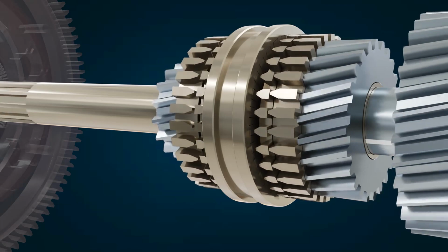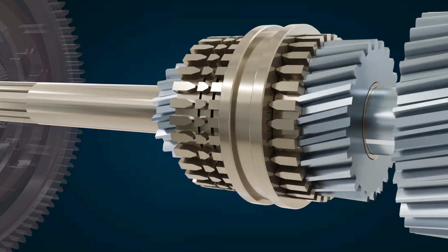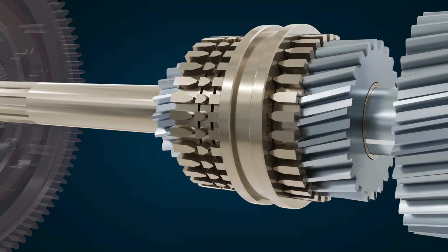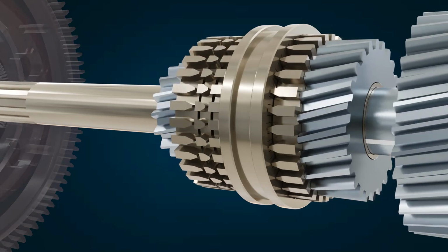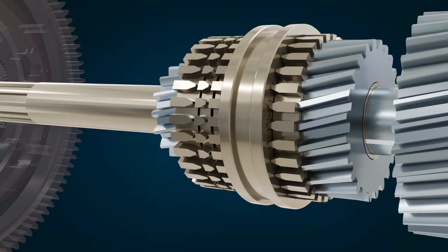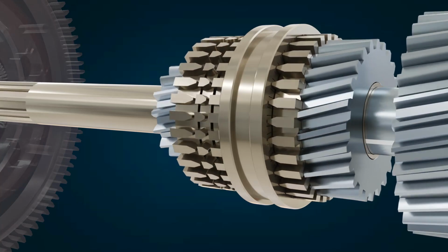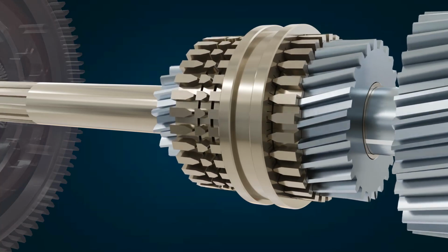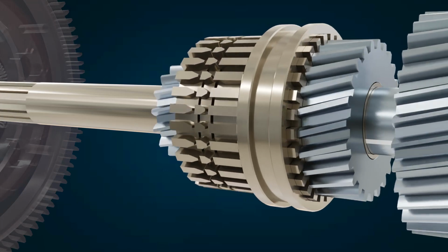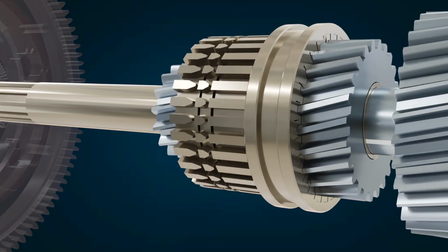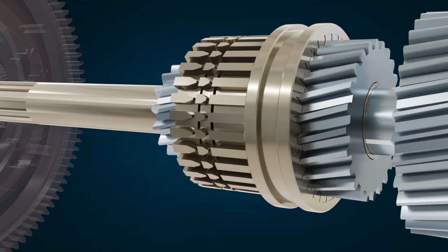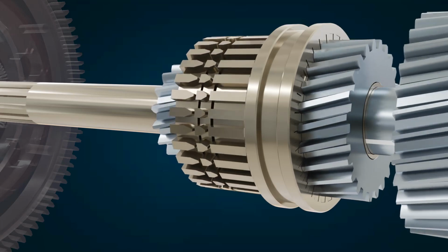When we move the sleeve, it will press the synchronizer ring against the cone. Due to the high frictional force between the synchronizer ring and cone, the speed of the gear will become the same as the shaft. At this time, the sleeve can be slid further and it will get locked with the gear. Thus, the gear gets locked with the shaft in an efficient and smooth way.